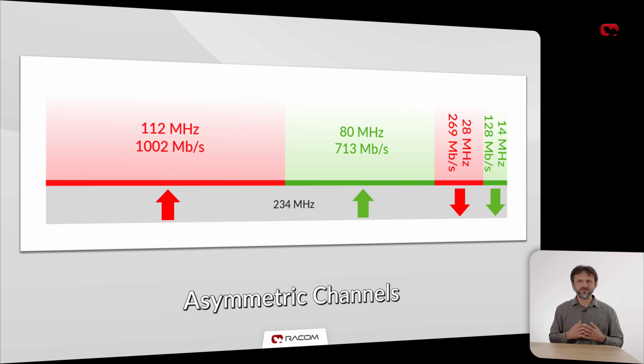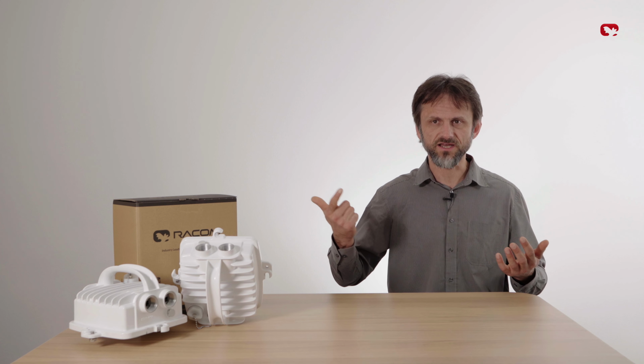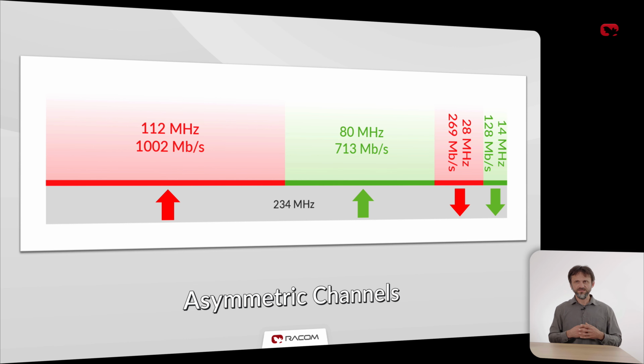Most of the Ray 3 product line members offer asymmetric channels. Currently, they can only be used in license-free bands due to licensing conditions. Thanks to asymmetric use of spectrum, you can build, for example, 2 asymmetric high-speed links instead of only one symmetric link. This can be even more important on noisy sites. Asymmetric channels allow you to go around noise using every hertz of spectrum available.